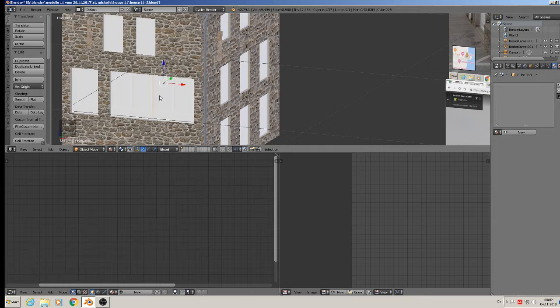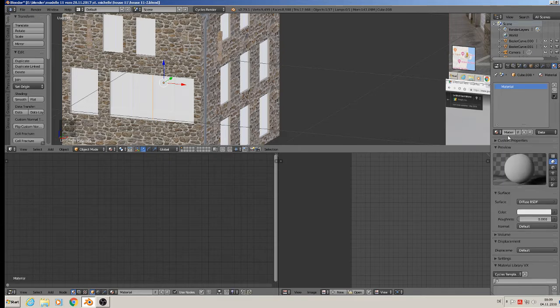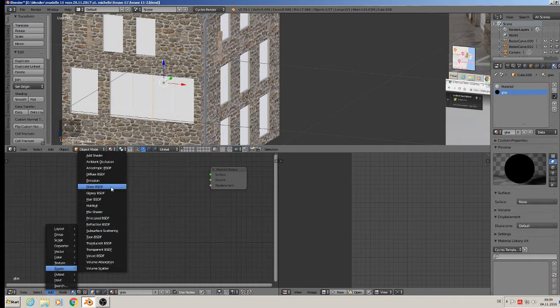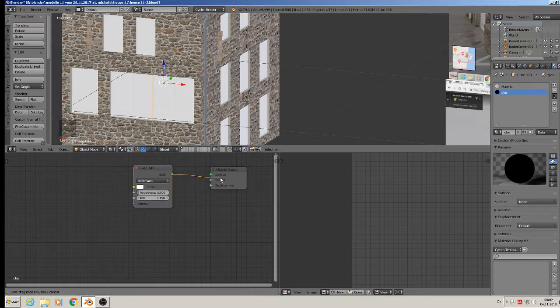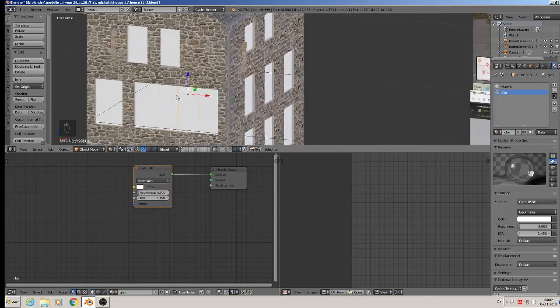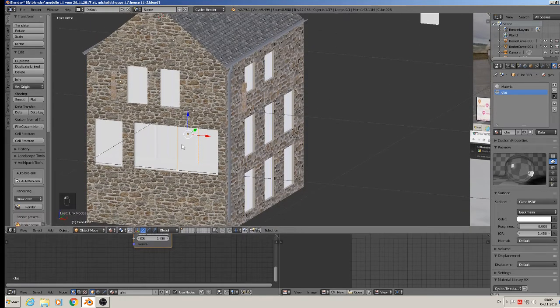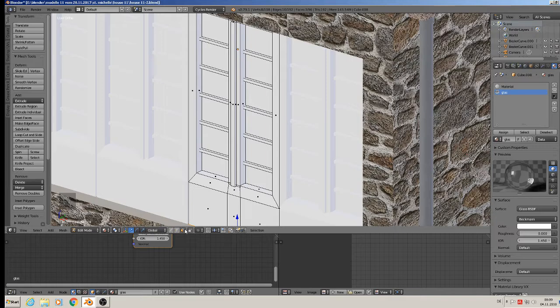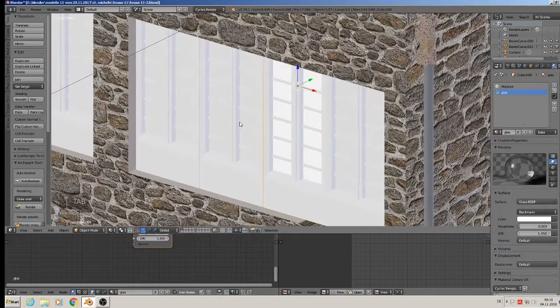Only the background of the windows should be glass, so we need a glass shader. And this part we make simple. Make a new white material, plus, new material, and call it glass. This glass material we make with a basic shader, nothing special. In the last tutorial I showed you how a correct glass shader can look. Here we take only a simple one, we don't need more, because it will all be baked later. That's all too much for this here. Good. And then the background should be glass, so assign, and then we have that.